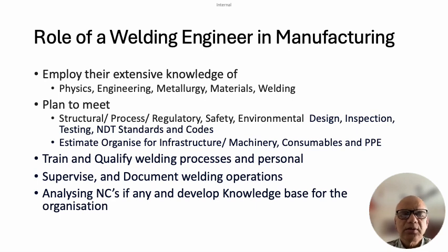Now everything is set, the job is already cut, rolled, machined, drilled, and setup has been done. Now he has to execute the welding, so his role is going to be like a supervisor, supervising the operations, that setups are coming in good condition, the cleanliness is maintained pre and post, and during welding controls are exercised, proper dress ups, and then offer it to NDT to ensure that the joints are defect free.